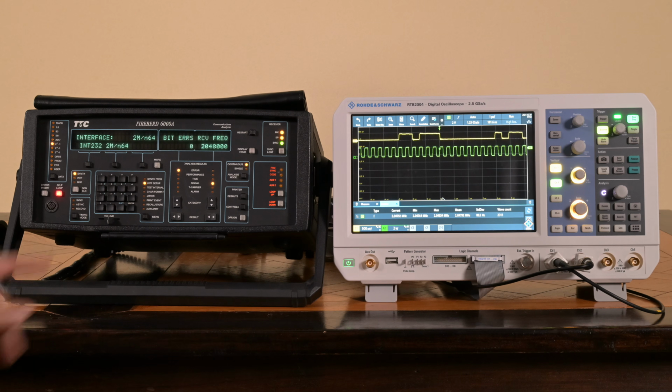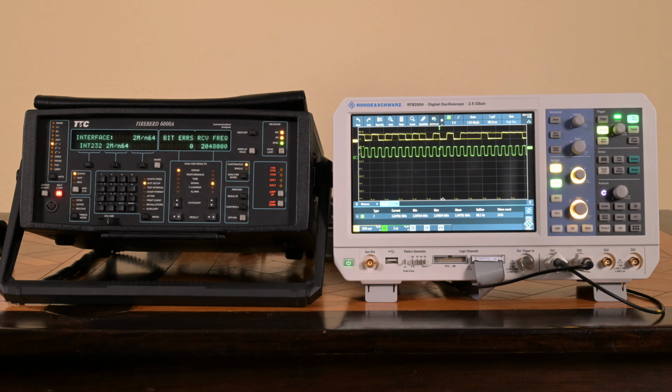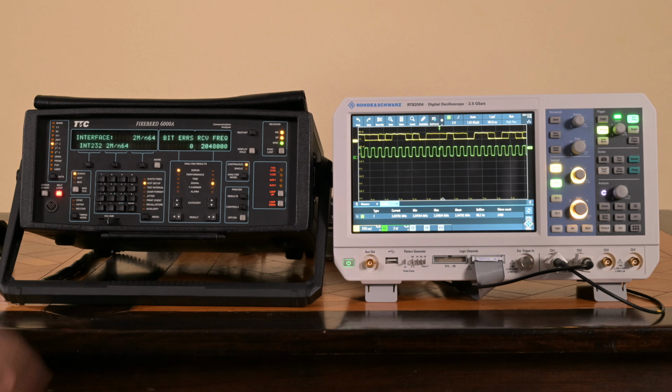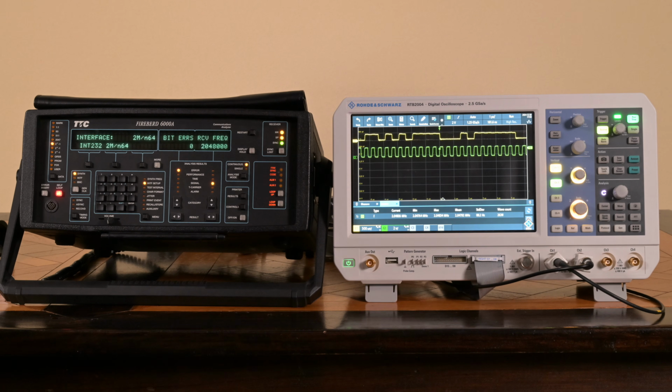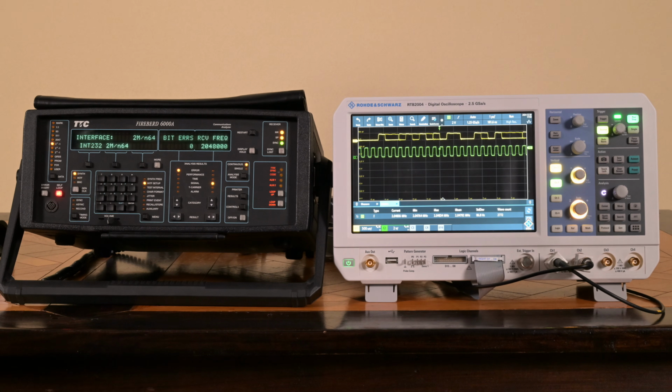So I set up the unit. It is running on the E1 interface. Actually, the jitter card installed in this unit is only compatible with the E1 European trunk interface. And on my other unit, I got a separate jitter generator and jitter analyzer card, but on the other unit, they're only compatible with the American T1 interface. So these cards are specific. This is a single card with both the generator and the analyzer, and the others are two separate cards to be installed in the unit.